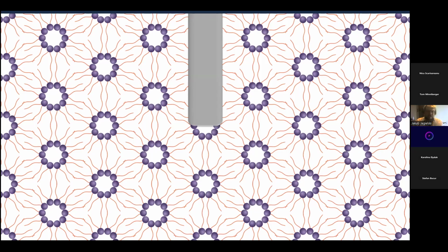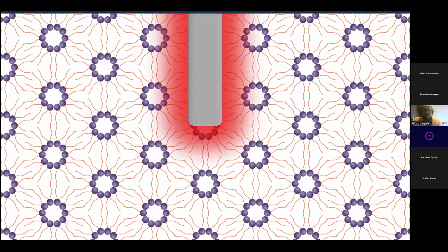Of course, these are applicable for biomedical applications. However, in my work, I want to use nanoparticles. To produce the colloidal nanoparticle dispersion from this bulk structure, we need to fragment the bulk mesophase. Here we see an ultrasonic probe being inserted into the sample, and using high energy acoustic cavitation, mainly homogenization using ultrasound, we can disrupt the bulk structure into nanometer scale fragments.